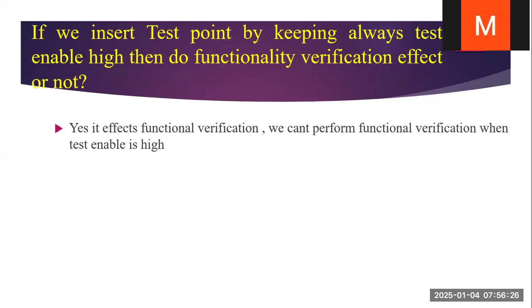So if we insert a test point by keeping the test enable always high, does it affect the functional verification or not? Yes, it affects the functional verification. We can't perform the functional verification when test enable is high because we have to toggle it 0 to 1 and 1 to 0.